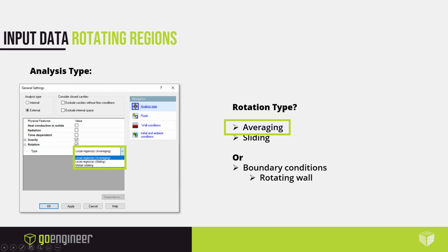It's a simpler approach, mainly because of the assumptions made about the flow field distribution. The assumption is that it ignores the rotational characteristics. What this means is that a majority of the flow enters and exits the rotating region axially. But the advantage of this assumption is that it is less computationally demanding. So, considering the assumptions made by the averaging approach, I may not want to start with the averaging method and instead maybe use the boundary condition to start.